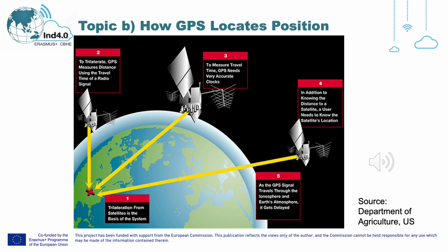The system is based on a constellation of orbiting radio navigation satellites, that is the space segment, an Earth control segment, and the receiver, which is the user segment. They provide continuous position data provided the receivers have line of sight access to the satellites. The receiver synchronizes its code with the satellites by adjusting the timing of its code generation until the intersection of all the satellites' ranging spaces converge at a single point.